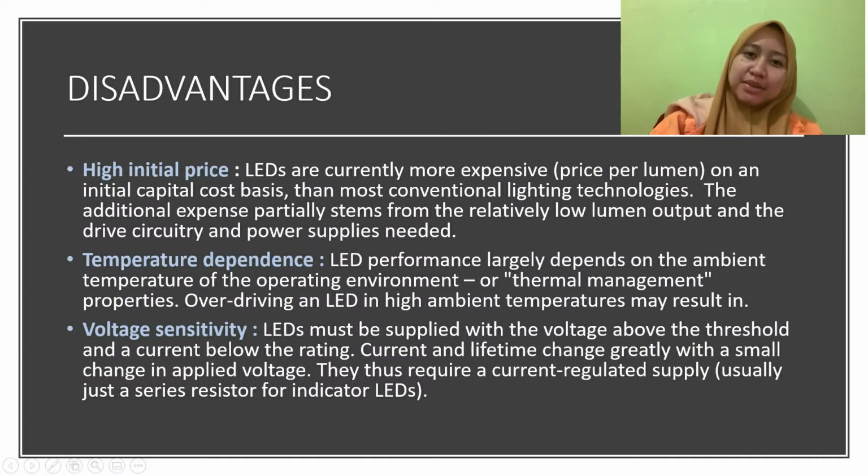Okay, LED displays have a few disadvantages, such as high initial price. LEDs are currently more expensive per lumen on an initial capital cost basis than most conventional lighting technologies. The additional expense partially stems from the relatively low lumen output and the drive circuitry and power supplies needed.